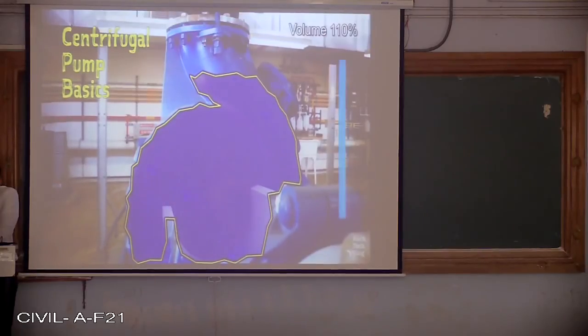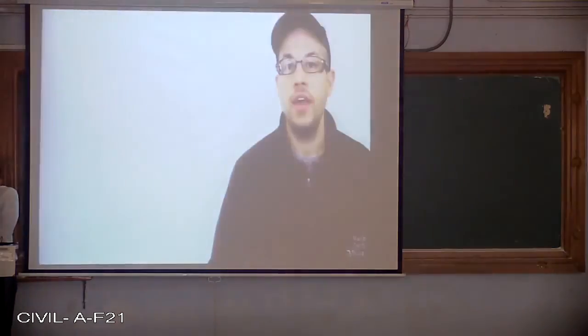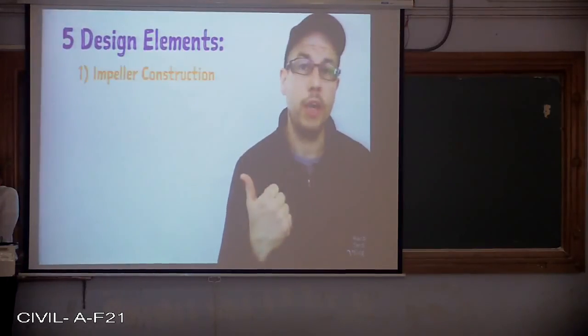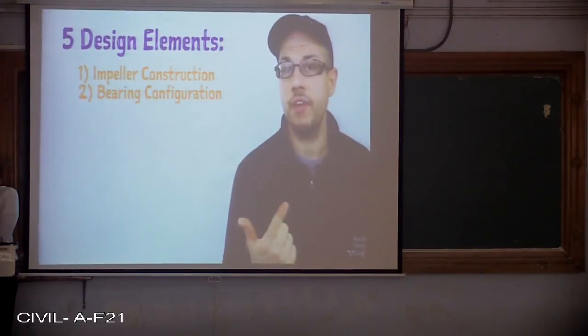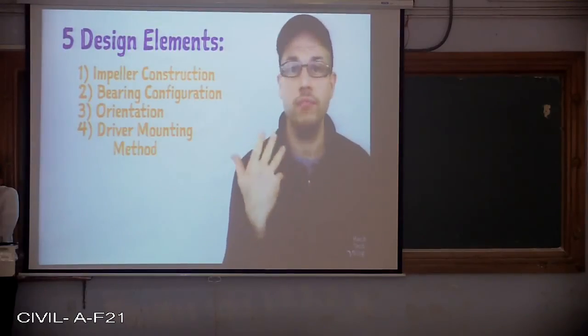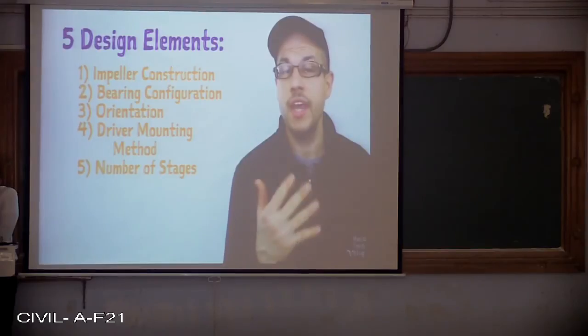All centrifugal pumps share this basic operating principle, but there are a few possible variations among them. There are 5 primary design elements to consider: impeller construction, bearing configuration, orientation, driver mounting method, and the number of stages.